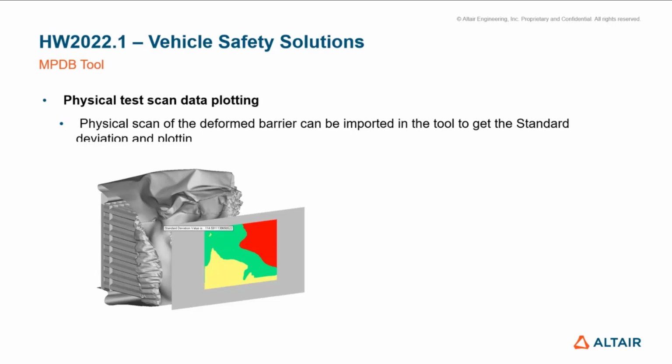So a customer who has done a physical test and has the possibility, for example, to scan the deformed barrier after the crash can import this data into the tool, which then will enable the plotting of the intrusions, as you can see on the screen in this picture, and the calculation of the standard deviation values and so on, which are needed for the post-processing of this load case.